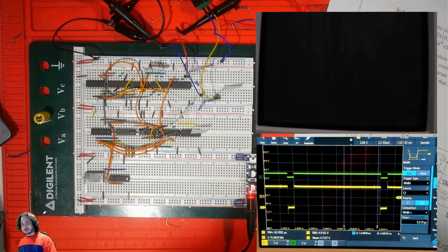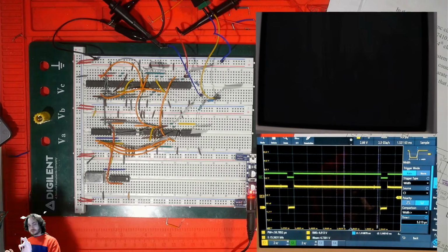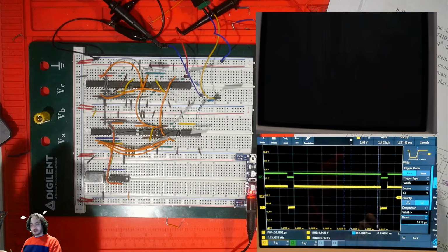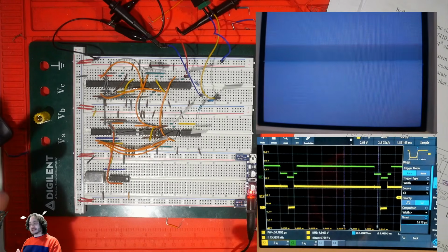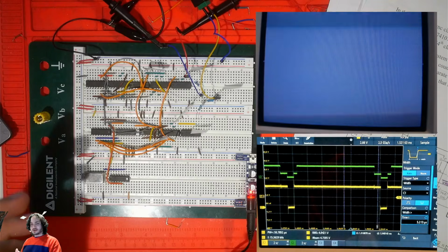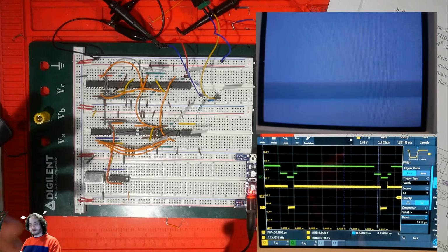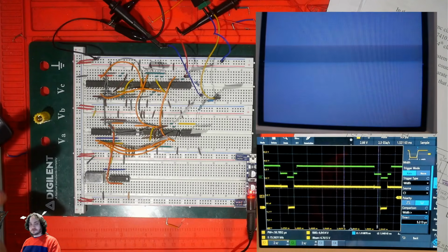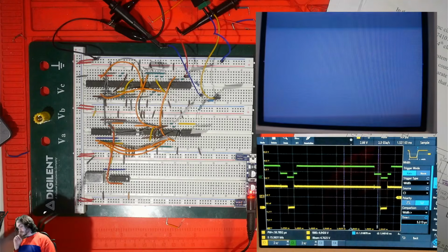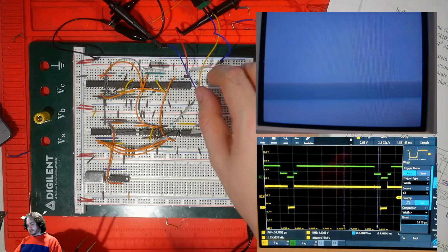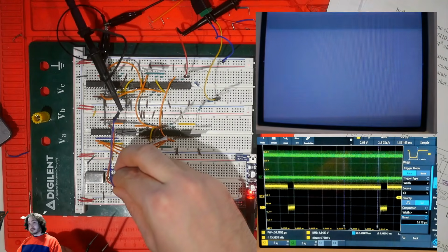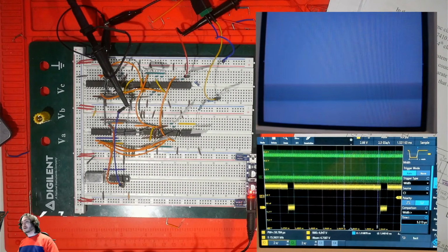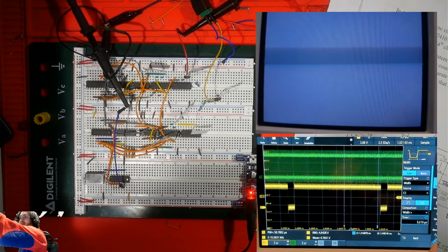the next thing we're going to need is to impose a color carrier signal onto this. Black and white TVs would have filtered it out. And when the color TV was invented, they added this as a backwards compatible way to have color and black and white TVs receive the same signal. Black and white TVs just display the grayscale version. And we already have the right frequency. We have a 3.5 megahertz guy here. Let's zoom in a little bit.